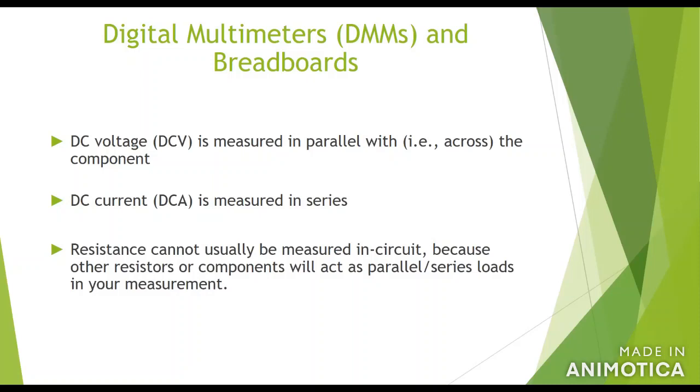You plug your components into the breadboard to make your circuit, and then you test the circuit. If you find that the prototype works correctly, then you can go ahead, make a PCB board, solder all the components onto the PCB board, and test further. So the breadboard is the first step you have to use to test your prototype.